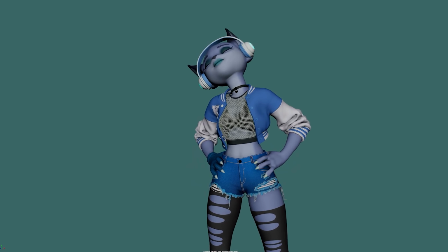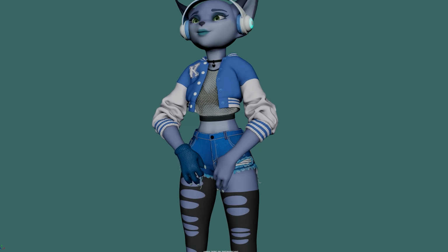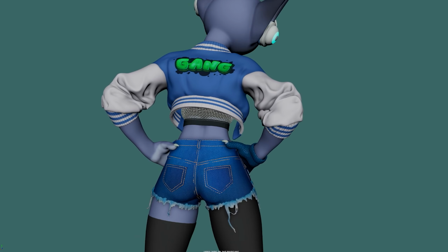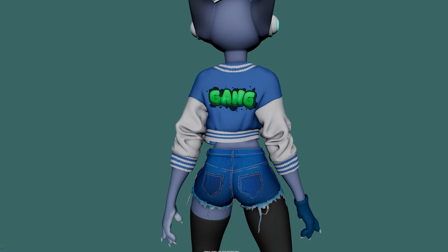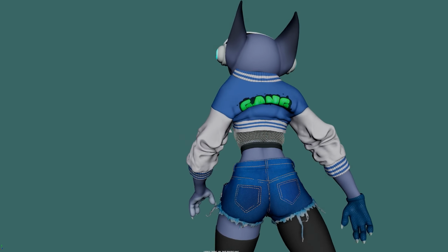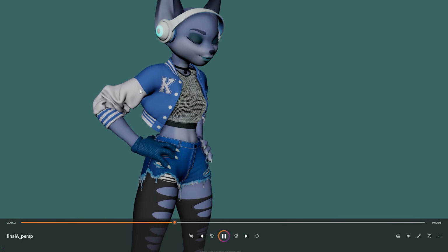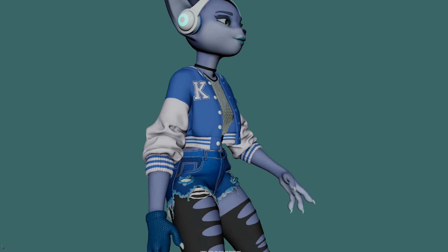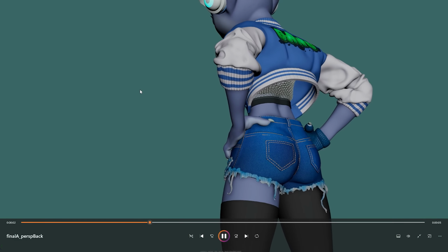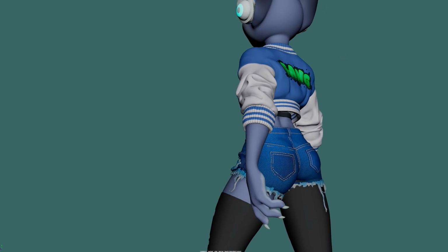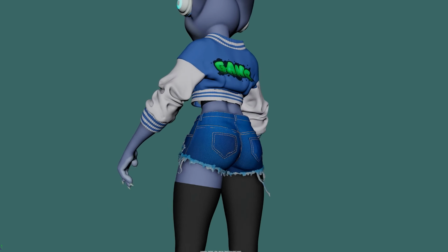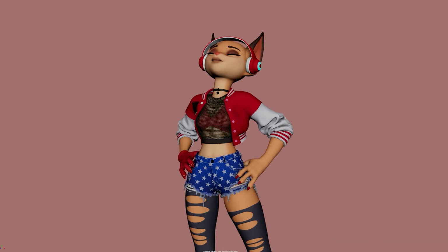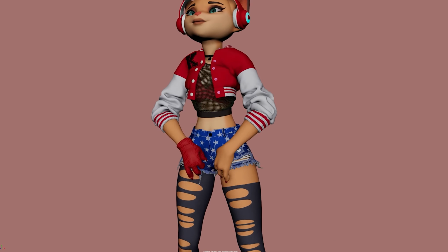Even though you watched me use this workflow for my project, it is important to understand that this approach may require some unique tweaks to work for your project. Leather and denim are some of the heaviest and most rigid behaving clothing materials. If you are dealing with lighter and stretchier materials, you will need to fine-tune compression, stretch, and bend resistance to your needs. If you are also going for a very hyper-realistic simulation, you will have to play with more dynamic settings.